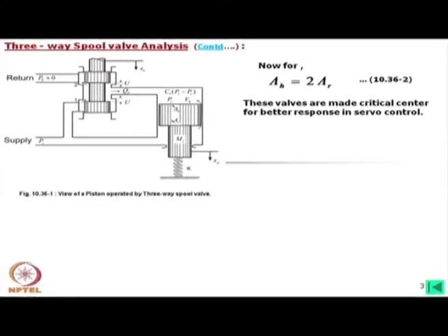this adjustment, because this is driven by some actuator, this might be an electrical solenoid. Now, adjustment with these solenoid positions and these spool positions, because the solenoid is not directly coupled, it will be directly coupled, but not a single component. The solenoid spool and this spool are not an integral part, they are just connected. So, sometimes it deviates from these critical center positions, and that can be adjusted of course.